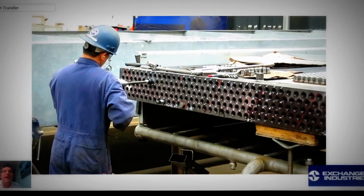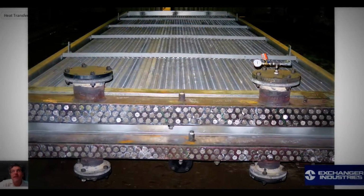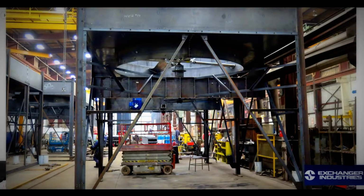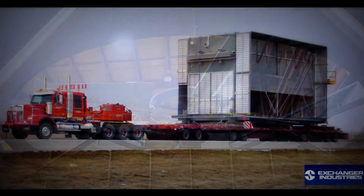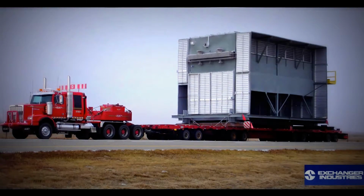And so for the aerial cooling units, we attach the tubes with the fins to the header box, and then this is what it looks like after. And here's an image of it being pressure tested to ensure everything is up to quality specifications. This is where it eventually goes. These are the fans that will circulate the air over the heat exchanger. You put it all together, you put it on a truck, and you transport it to the field.